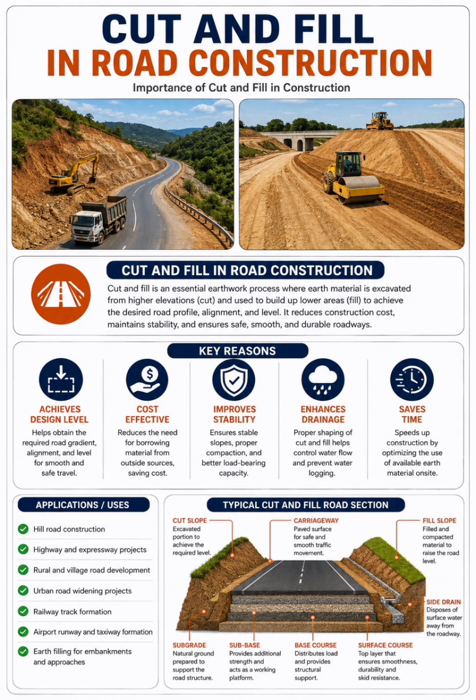So when you cut from that particular area, you test the material to see if it reaches the standard that is required for you to fill. If it is up to the standard required, you use it to build up the lower area, which is fill, to achieve the desired road profile, alignment and level. So it reduces construction cost, maintains stability, and ensures safe, smooth and durable roadways.